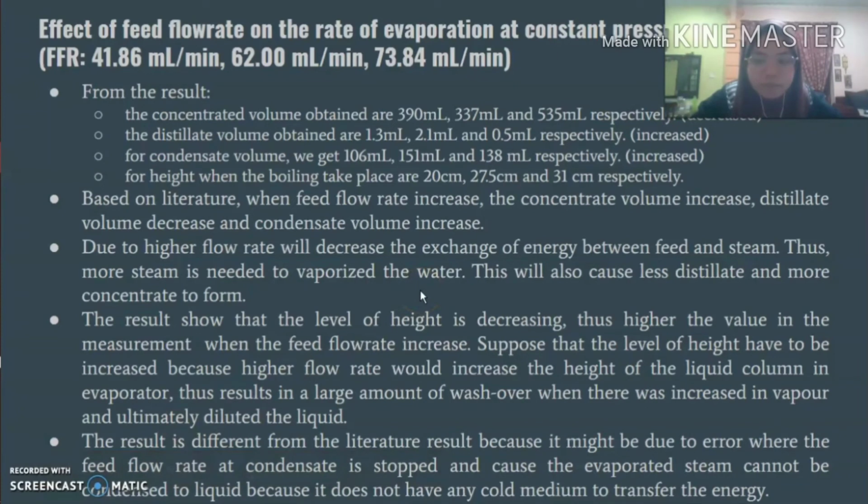And the result is different from the literature, it might be due to some error where the feed flow rate at the condensate is stopped, and causes the evaporated steam to not be condensed to liquid as it doesn't have any cold medium to transfer the energy.